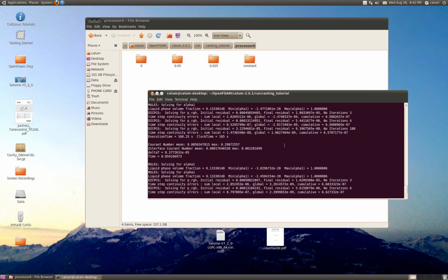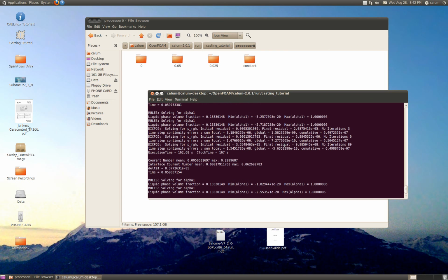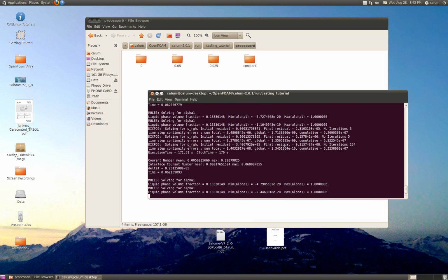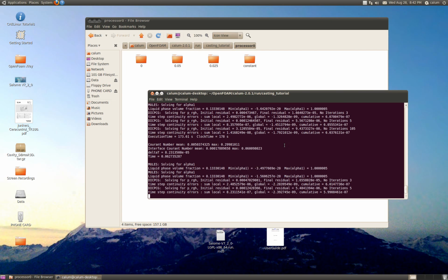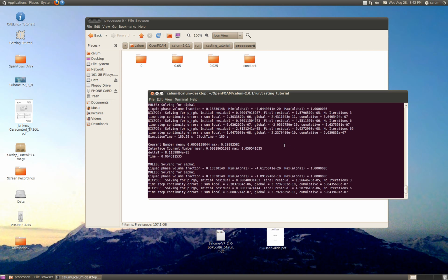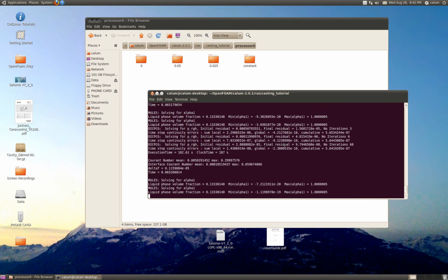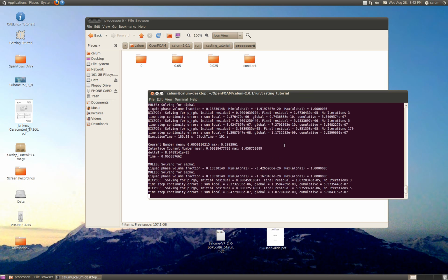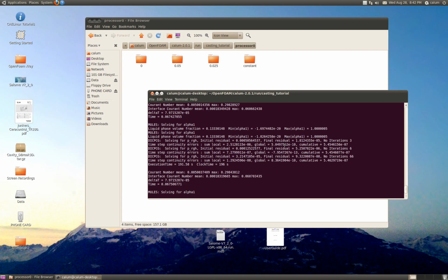Depending on your geometry, you can use an automatic function whereby you define your inlet and outlet patch, and then tell OpenFOAM to automatically call everything you haven't named the wall, given an angle change between elements.